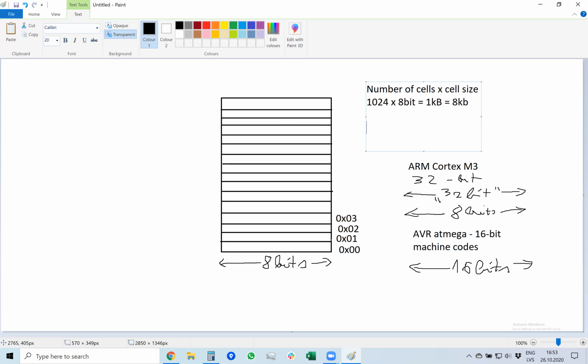So each data location is not 8 bits, but 16 bits. Or for example, if you make a data logger and you know that all numbers that you are going to store in the flash memory are 16-bit integers, well, then you can just buy 16-bit memory instead of buying 8-bit memory and then remembering to store the bottom part of the number in one memory location and top part in the next memory location, and addressing needs to jump over 2 memory locations and so on.